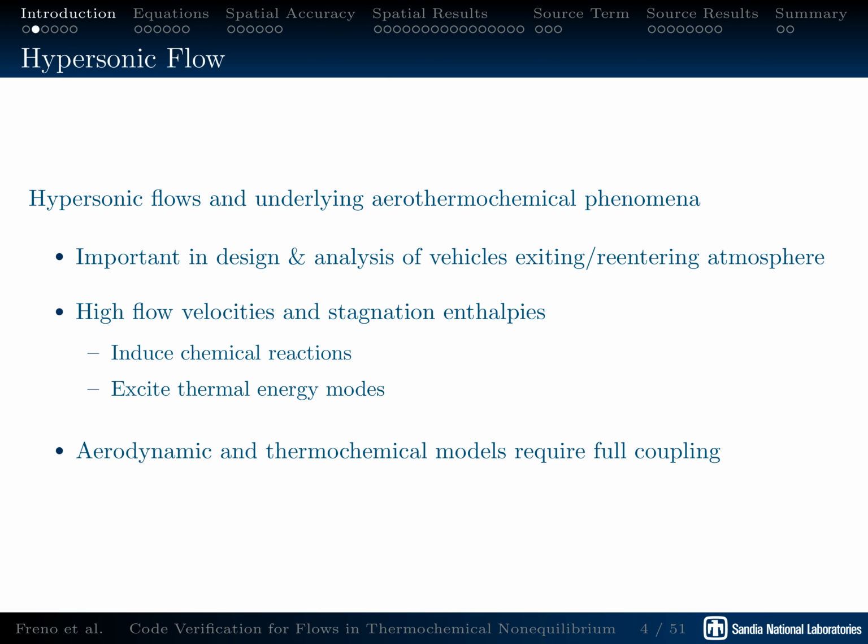Hypersonic flows and their underlying aerothermochemical phenomena are important in the design and analysis of vehicles exiting and re-entering the atmosphere. Their high flow velocities and stagnation enthalpies induce chemical reactions and excite thermal energy modes. As a result, the aerodynamic and thermochemical models require full coupling.